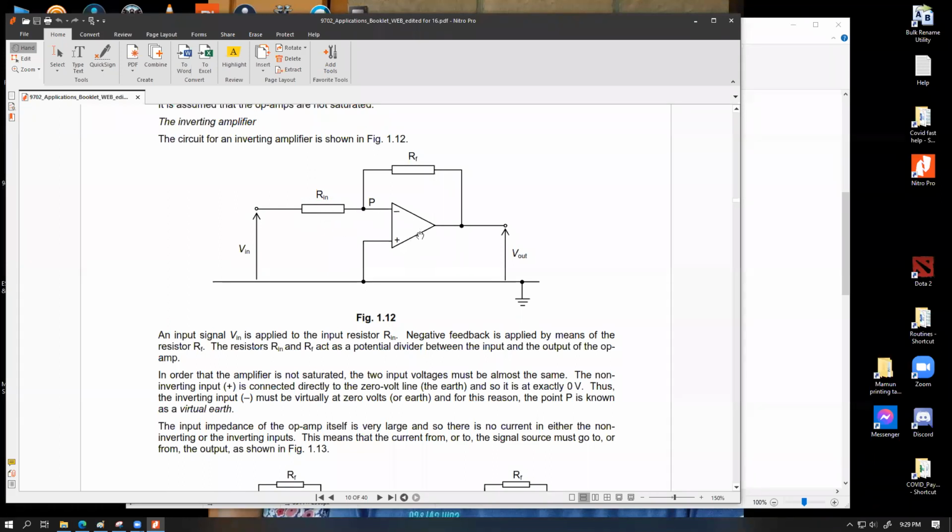And then we're going to have the whole thing provided as output. We're going to take a small fraction of the output, make it flow to a feedback resistance labeled as RF, and connect it right before the negative input, not here. Before the negative input. And P is going to be one of our connection points, and this P point has a very important approximation-based significance, which I'm going to explain.